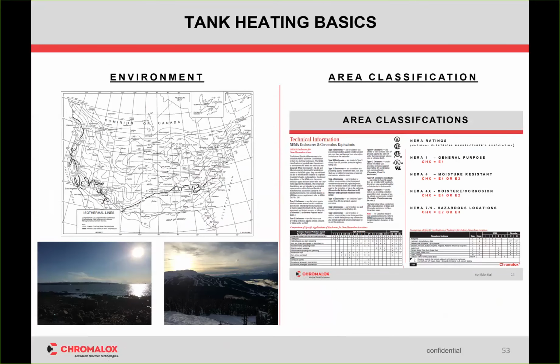And then environment. Is it by the ocean? Is it up in a mountain somewhere in the cold? Is it buried in snow? Easy things to discuss, but they need to be part of the conversation, because the data sheet says one thing, and reality is something else. The data sheet could not mention that it's sitting next to a port where salt water is hitting it all day. Well, guess what? I'm not going with stainless anymore.